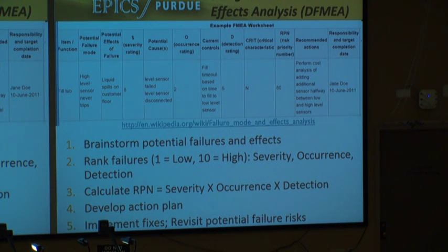You might identify that some of them are really not posing a very large risk at all, and you don't need to do anything to your design. But you absolutely would want to address those that have the highest RPN, or at least be able to defend your design decision to your design reviewers, to your future teams, on why you did not do this.